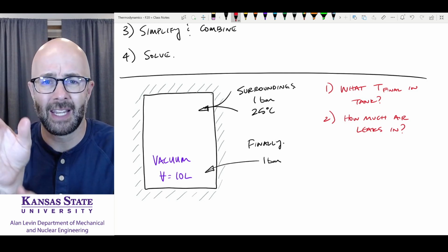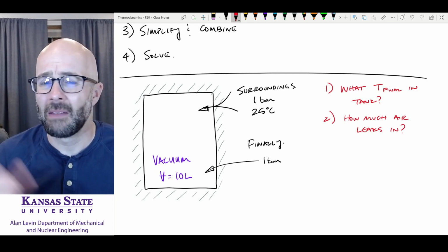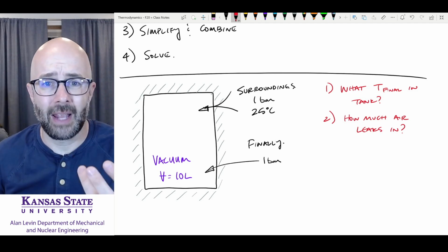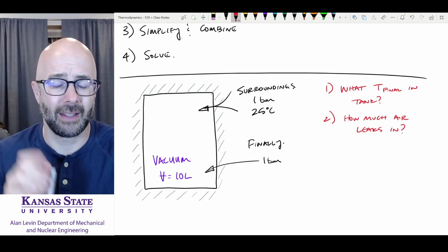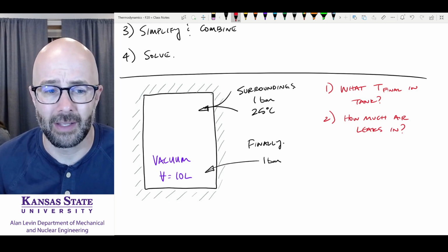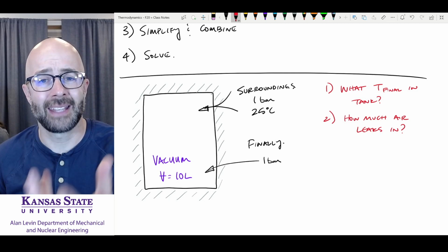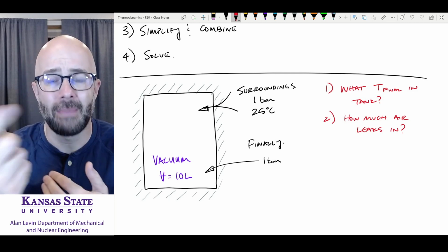You've dealt with a container maybe of air, compressed air, or maybe just even a spray paint can that you sprayed. That's a transient system because the mass is changing with time as it's leaving. It's not steady state. The mass in that spray paint can is going to change with time. And as you sprayed it, if you hold it down, you're going to notice that can is getting colder. Okay, the can is getting colder because of the mass leaving the system.